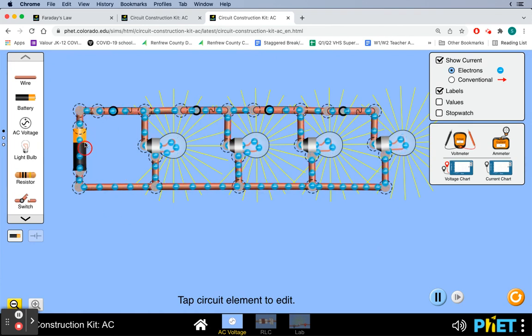So that means that the current from the source has to increase. And so this is a potentially dangerous situation. If you just continue plugging devices into the outlet, the current is just going to keep increasing. And this can get to a point where some damage can perhaps be done.